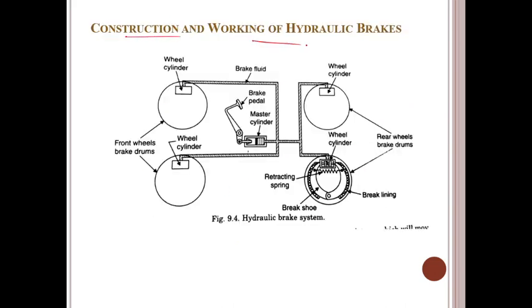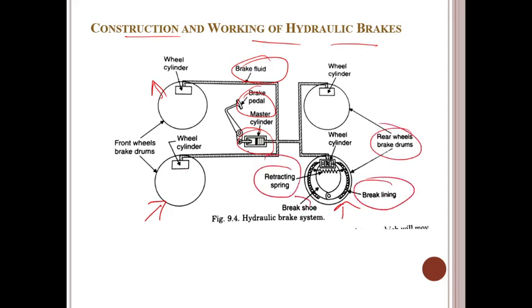So what is the construction and working of the hydraulic brakes? Look at this, guys. These are the front wheels. This is our design. There is a piston and there is a cylinder. This is our master cylinder. This is the brake pedal. Inside the pipe there is brake fluid. This is our rear wheel. There is a retention spring, brake line, brake shoe, and wheel cylinders.